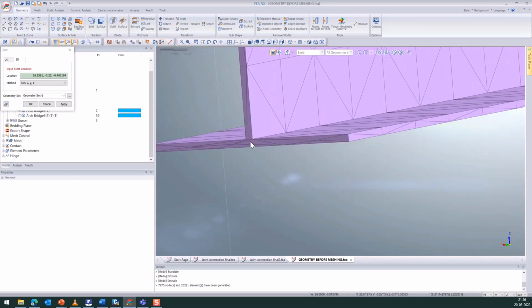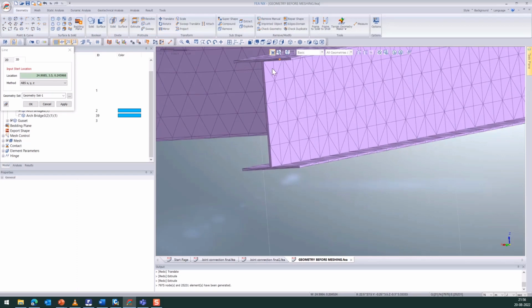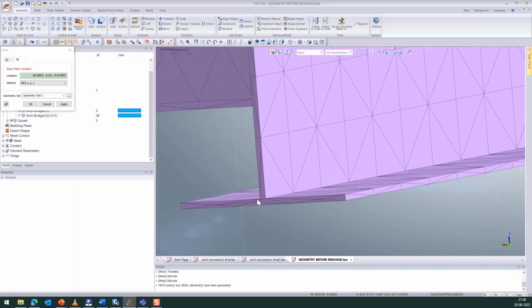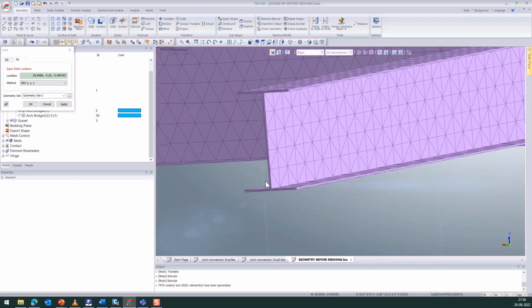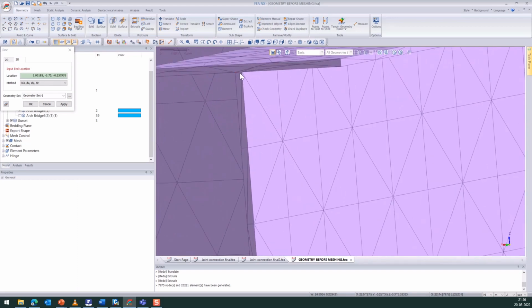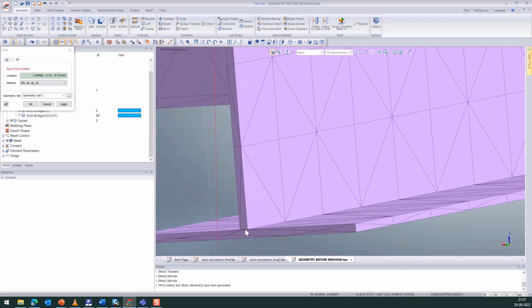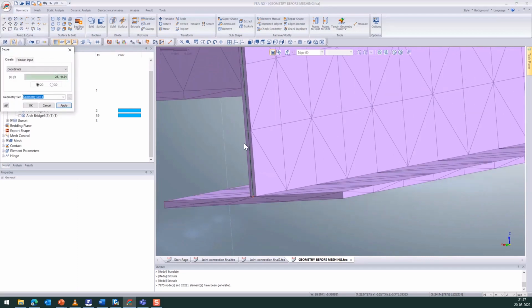So I'm not able to identify the node, so rather I'll check whether the node is available at the center. For that, I can create a center node between these two and create an intersection. So let me just do that. Create this line, create this line. Now create a connecting line from center of this to the center of this, as we can identify the midpoint of this. Now let's create points at the center of these particular lines.